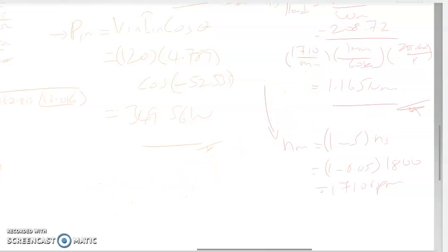And G is your efficiency. Efficiency means the amount of your output power divided by how much you put into the system, P in, times 100%. So we have calculated that the output is 208.72, input is 349.56, so times 100%, you will get your efficiency of 59.7%, and it is quite low because a lot of losses happen in between.